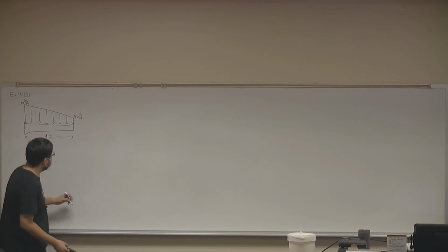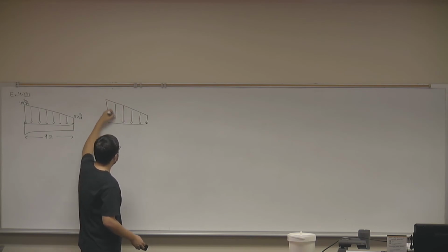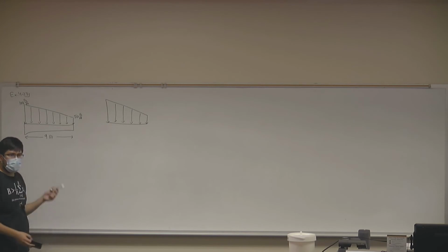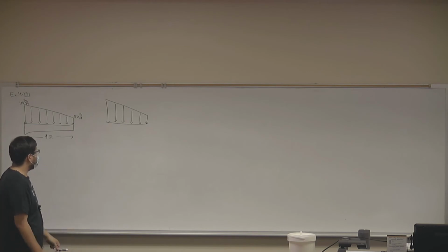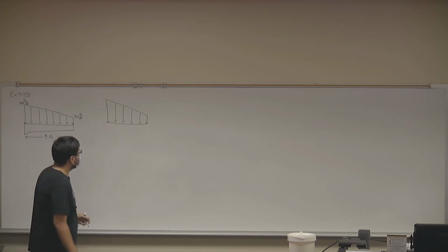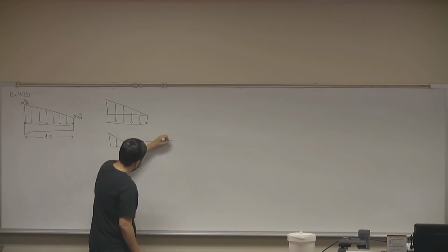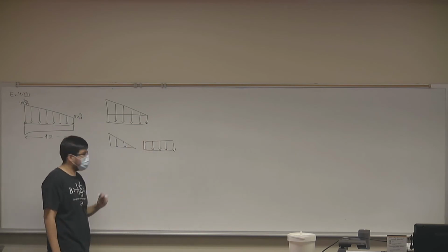This is a trapezoidal load. Now, there's two ways we can approach this. You can find the area of this trapezoid, but it's actually quite easy, right? Average of 50 plus 100, so 50 plus 100 over 2 multiplied by 9. Or, there's another way we could solve this. What's the other way? Cut the triangle off the top of the rectangle. Okay, so break this down into a triangle and a rectangle. Good.